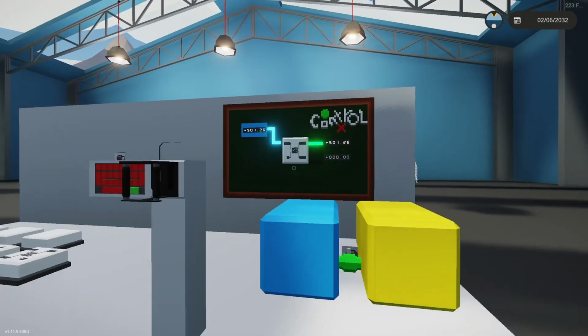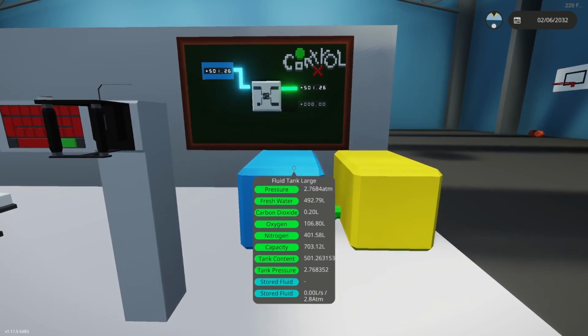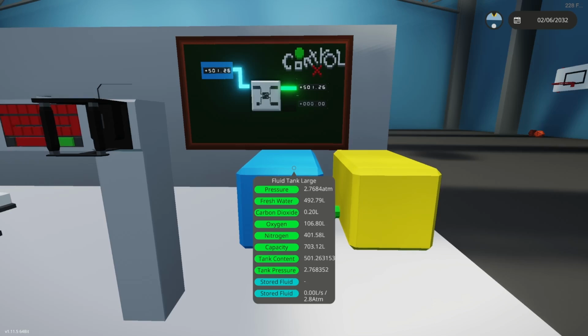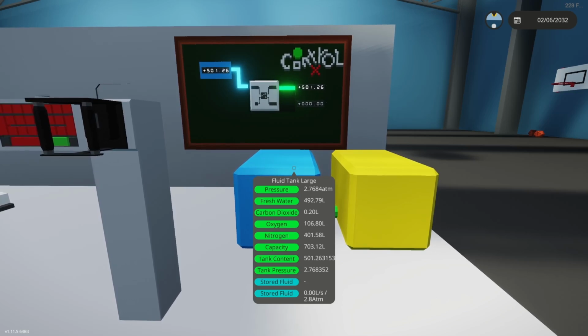Well, I used it for changing out control inputs for going to a VTOL. For example, if you're doing a VTOL and your yaw output is controlled through the rudders, but then you switch to helicopter mode, so to speak, you now want it to be controlled by your engines on your wings. Whether you're using pitch or rotating the engines, you want your yaw out there. And that's where you would send your yaw data instead of to the rudders.